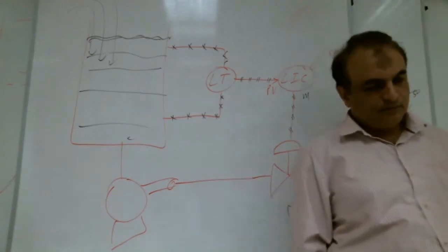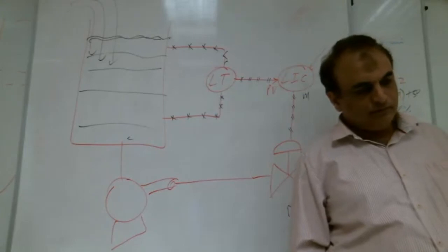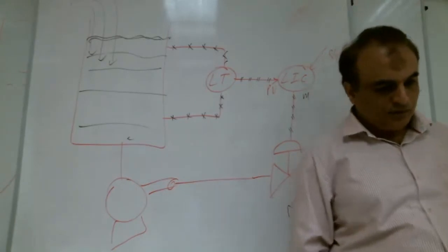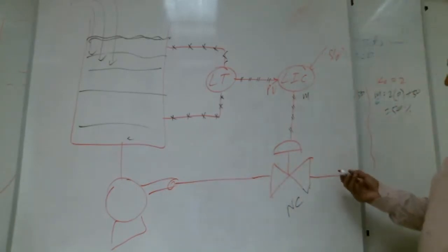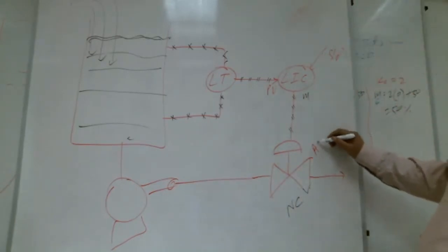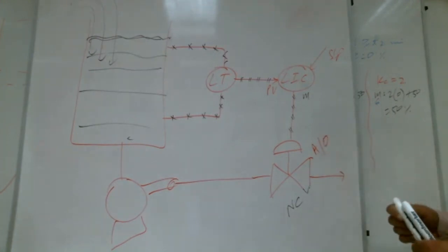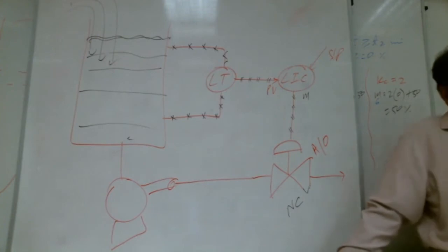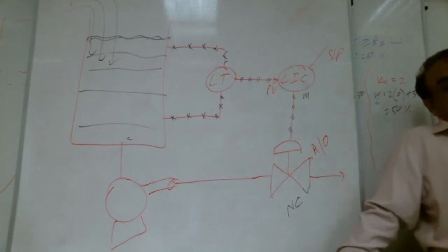What is the action of the control, direct acting or reverse acting, if the control valve is air to open type? Give the reason. This is saying air to open. Air to open means what? Is it normally closed or normally open?